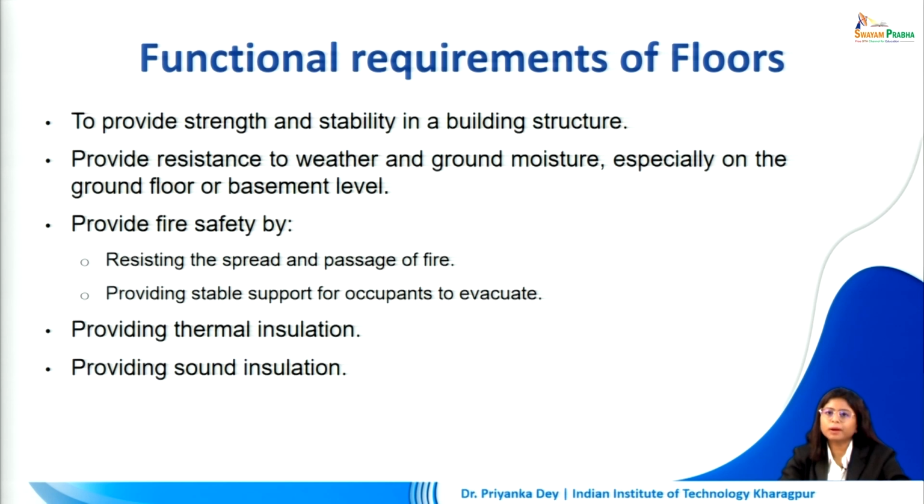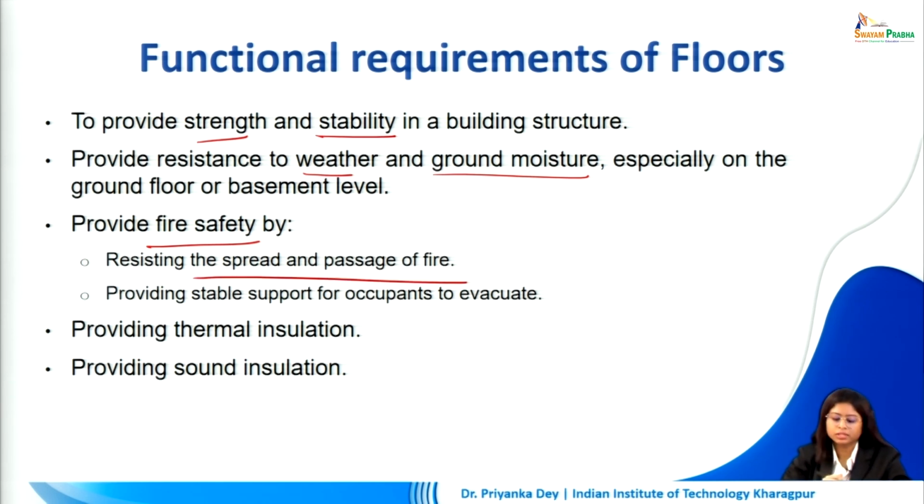Some functional requirements of the floors include that it provides strength and stability in a building structure. It provides resistance to weather and ground moisture, especially if we are dealing with the basement or the ground floor. It provides fire safety such that it resists the spread and passage of fire, and it provides stable support for the occupants to evacuate. It provides thermal as well as sound insulation, which is extremely essential if you are looking at multi-story buildings.